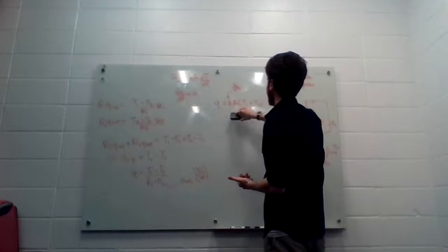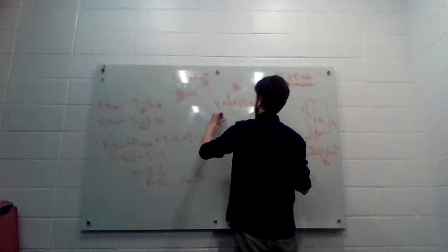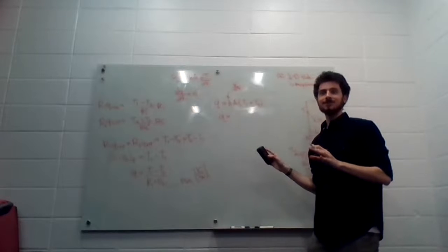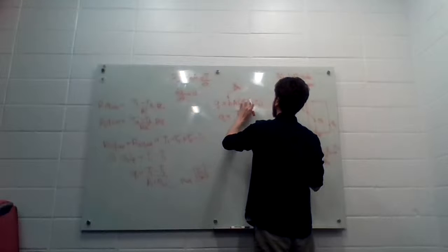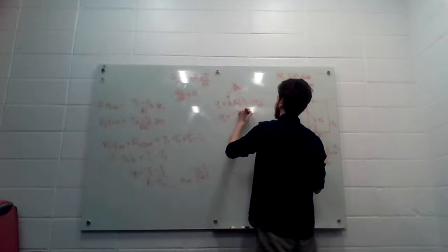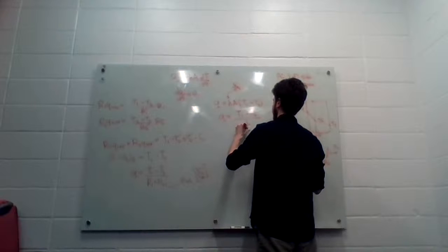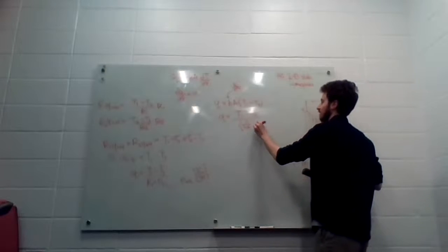The critical thing you can do with convection is you can make a thermal resistance too. So we can just bring, and this should be even more unnerving to you as people who are used to simplifying your fractions, oh, I'm sorry, it's T1 minus T2. This feels like a sin. This is wrong. But this is how you get your convective R.